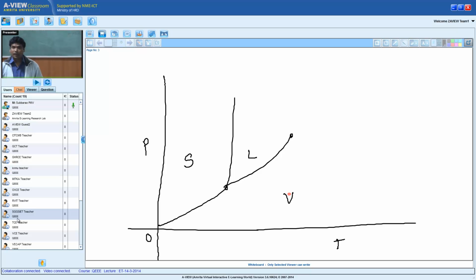So what I am looking for is this relation. For every substance I want to know the shape of this curve, the relation between the pressure and temperature, where liquid and vapor both are possible, because this is the border between the liquid and vapor. If I move along this particular line, both are possible. And what is the percentage? I need to know more. Now the question is, in order to develop this line, can this line extend to infinity? And very funnily, this particular line will not extend here at all.